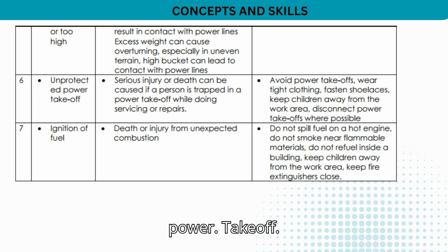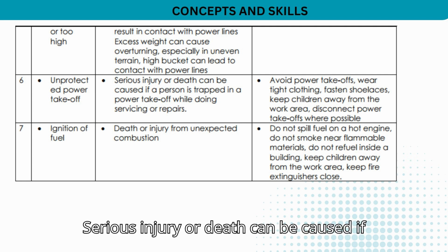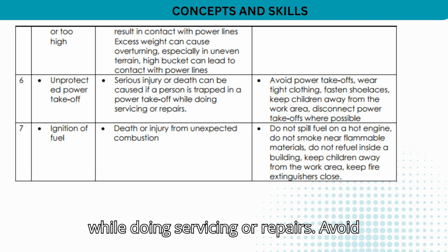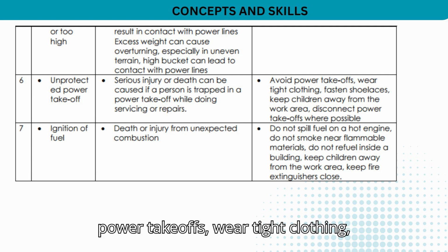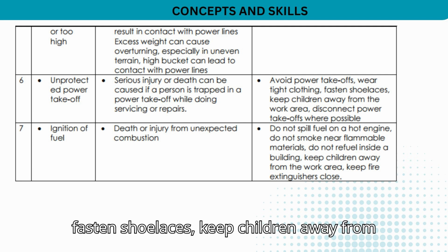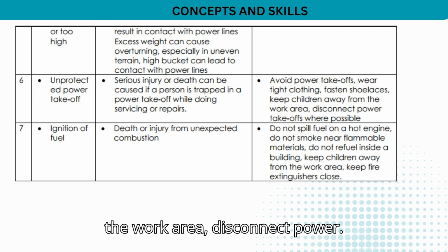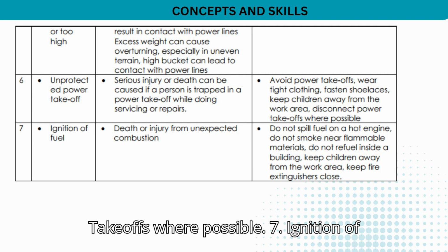6. Unprotected power takeoff. Serious injury or death can be caused if a person is trapped in a power takeoff while doing servicing or repairs. Avoid power takeoffs, wear tight clothing, fasten shoelaces, keep children away from the work area, disconnect power takeoffs where possible.